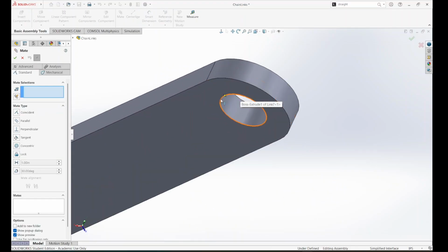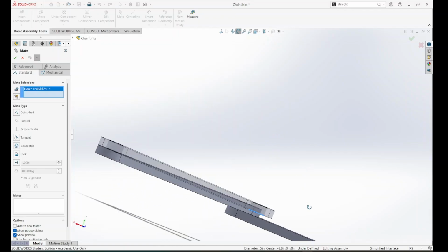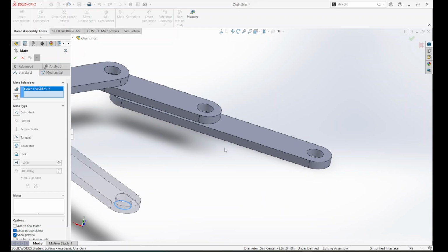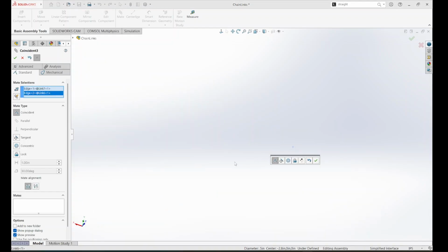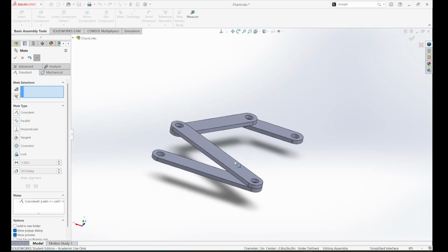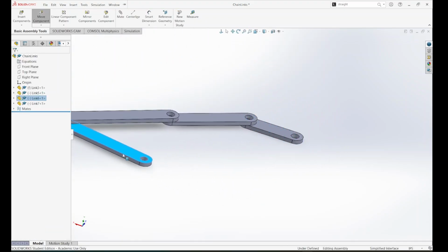We're going to click the bottom. Again, just be very careful that you click the bottom there. Perfect. It takes some little maneuvering here. I want it to attach to the top of this one. So let's zoom in, click. Awesome. And look, I was able to figure out where I am now. So go ahead, click the green check mark, move over. Let's get out of mate one more time. And boom, we can see that all of these are connected.